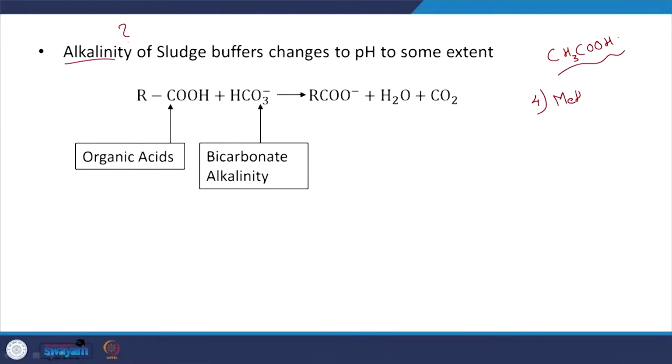And in that context, we saw that the microbes that lead to these steps, acetogenesis, thrive and grow faster than the ones that remove this acetic acid from your solution, right. So, that 4th step, which is relatively slow, is methanogenesis, right. And so, if this acetic acid is not being removed via methanogenesis, as you can see, it is an acetic acid, its pK is 4.76.